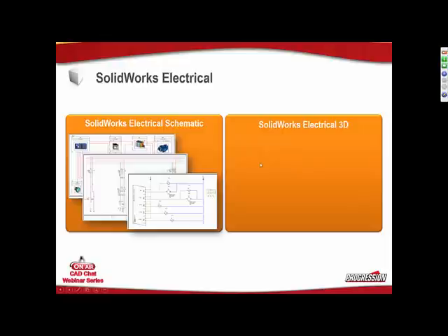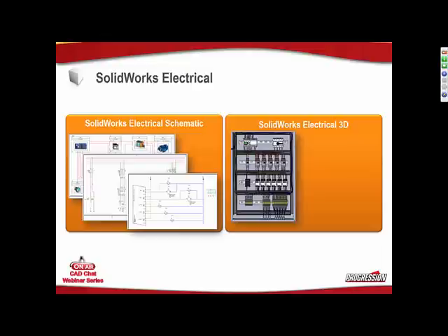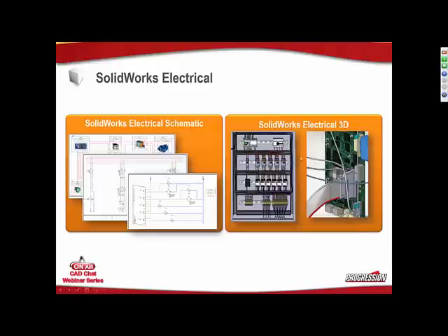And then we have the 3D side of things. The 3D side of things is, of course, an add-in for SolidWorks. And this is where you actually do the physical wiring. You add your components to your assemblies, and then you route wires and cables and harnesses. And then your harnesses, you can then flatten them out.